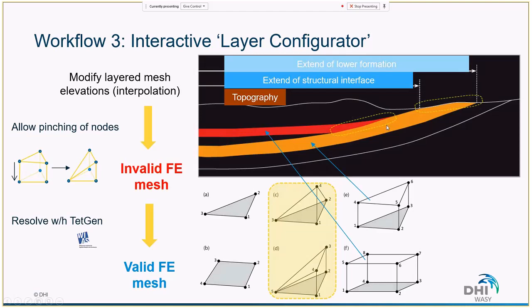Then you are done with this layer, and you can go with the layer in red color and repeat the same process. Then there is this conflict of a slice or layer intersection. The software offers you multiple options for how you can handle this. If you want to do it in the classical way, there is an option where you can preserve the layer continuity. This means that FEFLOW will maintain a minimum thickness in these intersecting areas.